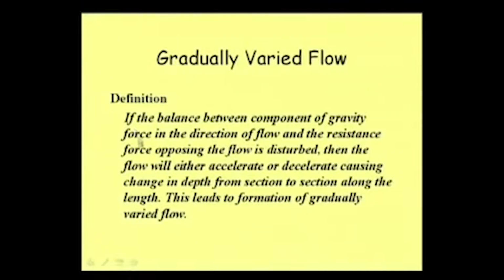When this is disturbed, the velocity will change; either it will accelerate or it will decelerate. And when the velocity is changing along the channel, then its depth will also change. So that way we get gradually varied flow. You can concentrate on the slide and we can define it like that. If the balance between the component of gravity force